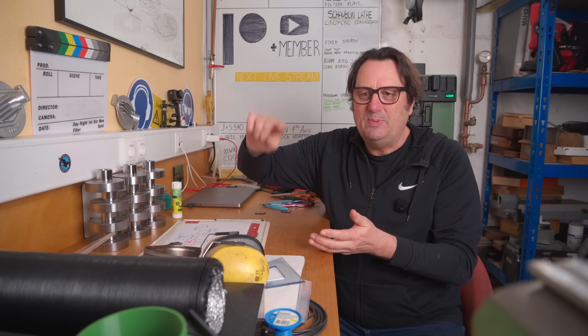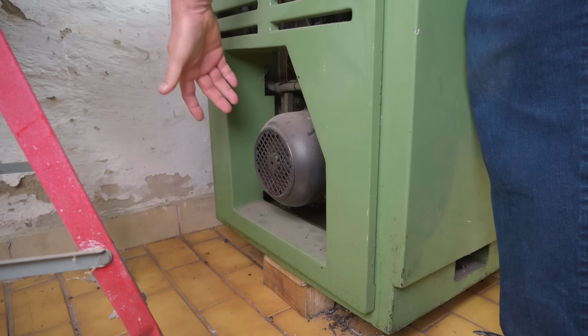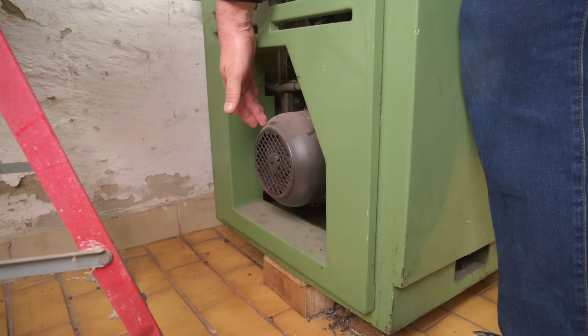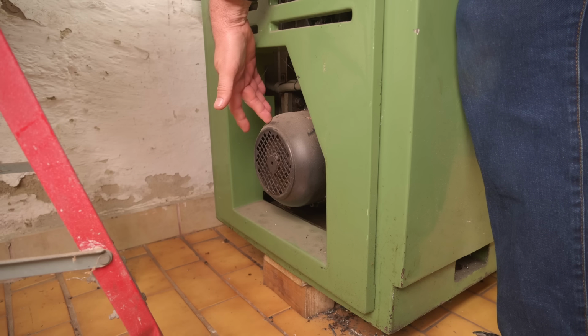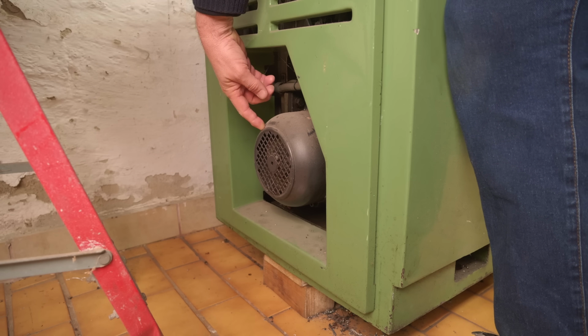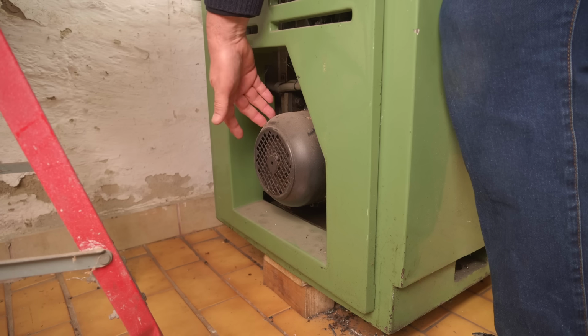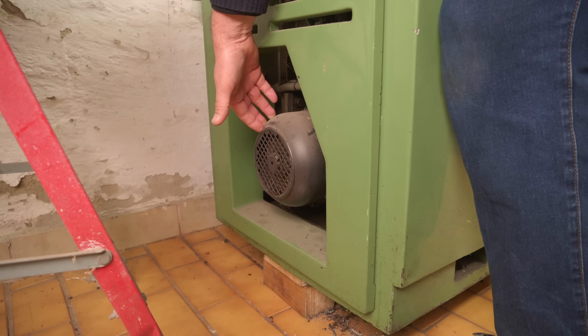The challenge is to get it also usable with constant surface speed cuts and fast enough reacting that I don't end up having these big changes in speed and speed over and undershoots during a constant surface speed facing pass. However, I am rather losing confidence in this way of inferring motor speed through commanded speed and then trying to work out the gear ratio of it. I am wondering whether I'm going to be forced to bodge a spindle encoder onto the back of this motor as one way of getting better data to calculate that ratio from.